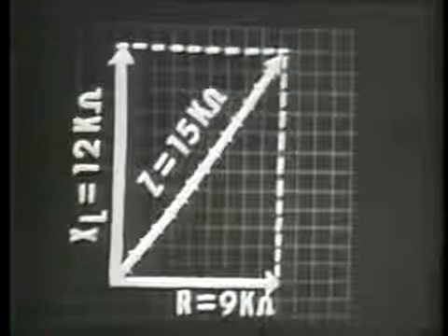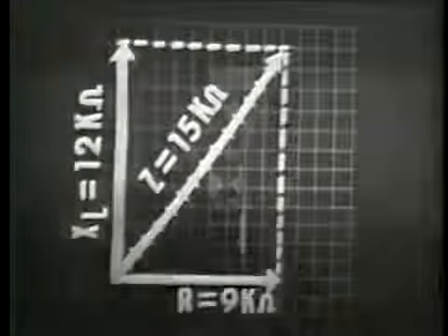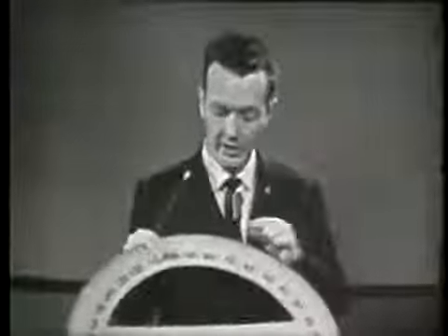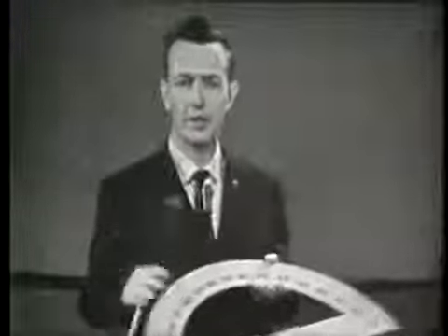If we had a protractor, we could actually measure the number of degrees in that impedance angle. Now, we know, being an inductive circuit, the impedance angle will be somewhere between 0 and 90 degrees. If we'd have measured ours, however, we'd have found it to be approximately 53 degrees. That is, a positive 53 degrees.